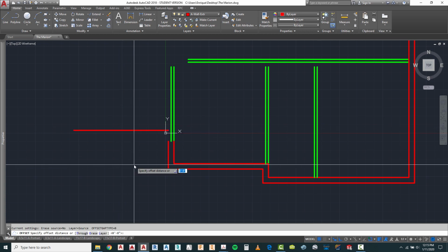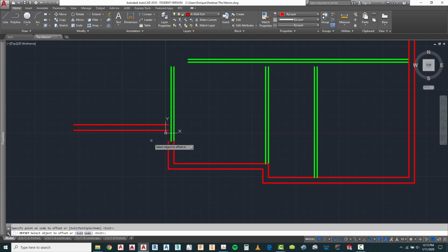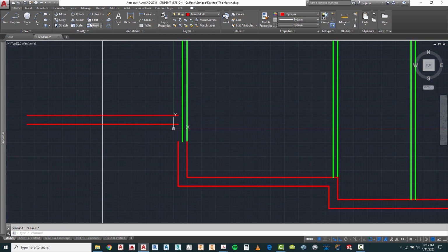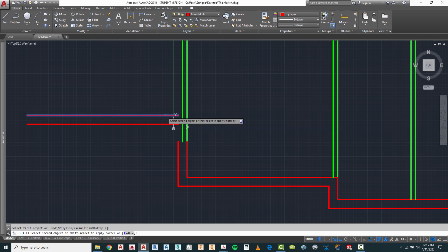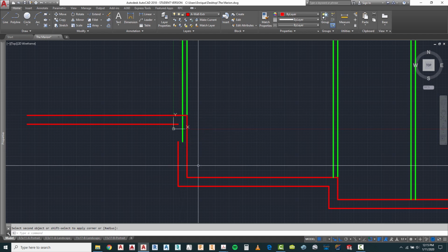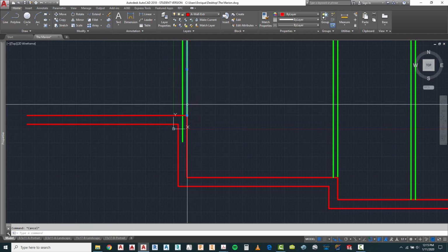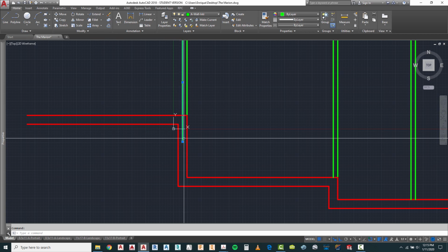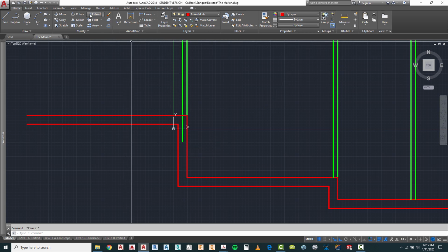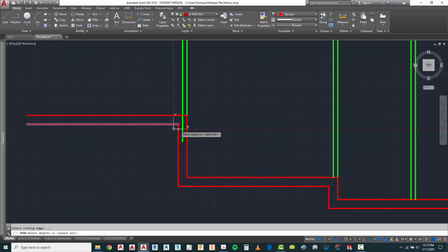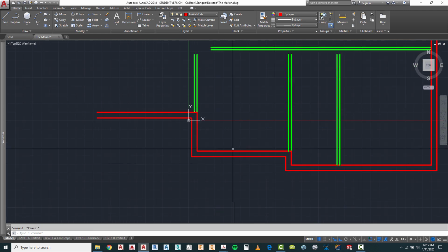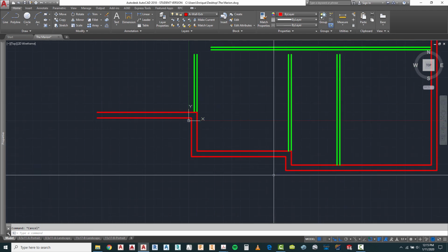I'm going to offset it 8 inches to the inside to give me the thickness of my wall. And then using the fillet command or my trim command, I can begin to fillet the different walls that I want. I'm going to fillet these two here again. I need to know where this one is. That's good, but this one I can either grab by the grip or I can go to my trim command and use the trim and trim that line out of there. So now I've got the same condition here as I have right here.